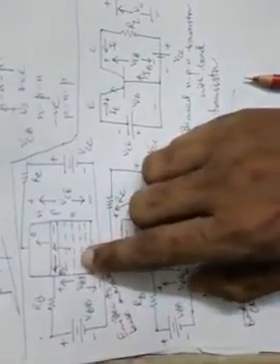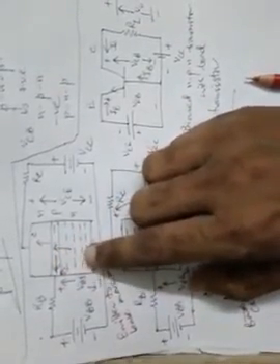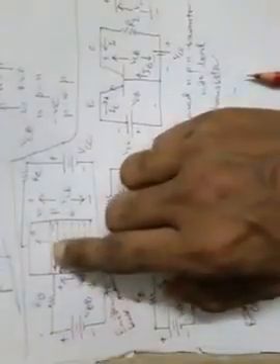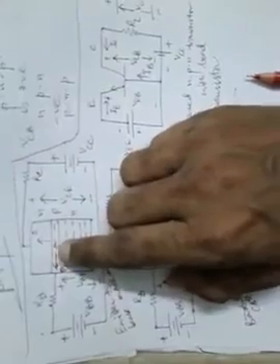So not much time for the electrons will be required to remain at the base area. Because of that, they will immediately move into the collector area. So the very thin base will help the electrons to move more towards the collector area than to go out through the base terminal towards the left side. So this is one reason.